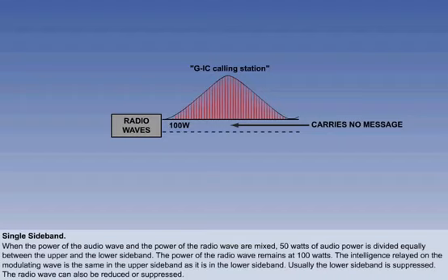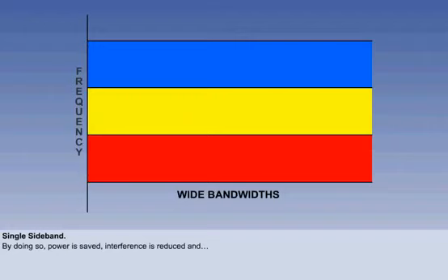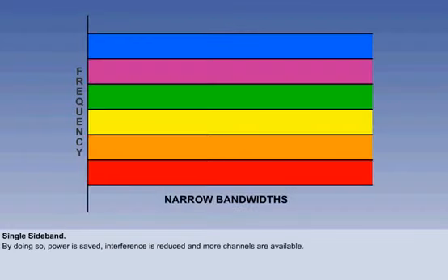In addition to the power saving, it is desirable to reduce the overall width of the transmission because sky waves are liable to distortion in the ionosphere. The narrower the width, the less the distortion and the better the signal-to-noise ratio. Because of the demand for radio frequencies in the MF and HF bands, there is an international limit upon bandwidth of 9 kHz in AM sound broadcasting. So, using narrowband transmissions increases the number of channels available.